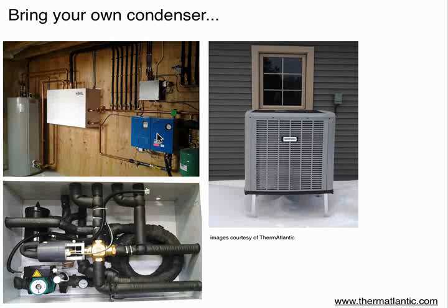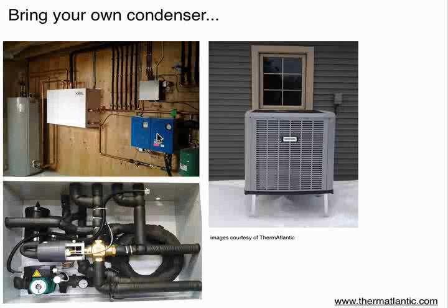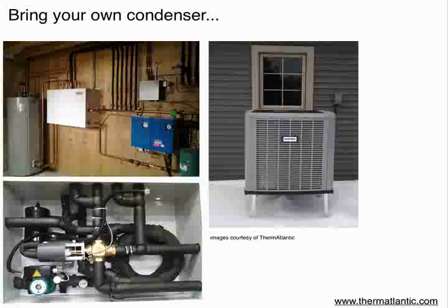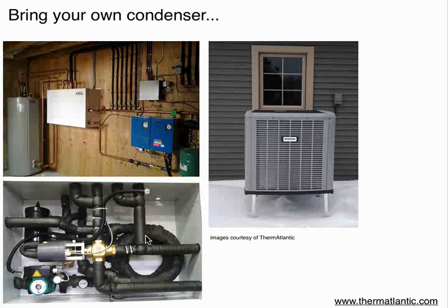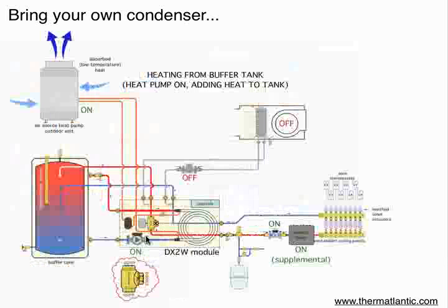And in particular, in the cooling mode, it can use the radiant panel for sensible cooling, and it can use the air handler to do the latent cooling, or the moisture removal. You'll see inside the unit here there's a mixing valve, a circulator, and a coaxial heat exchanger, and it's a pretty well thought out design. Here's an example of how the unit would operate in the heating mode.